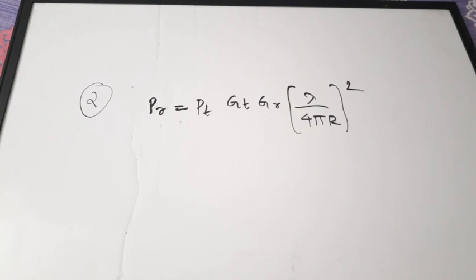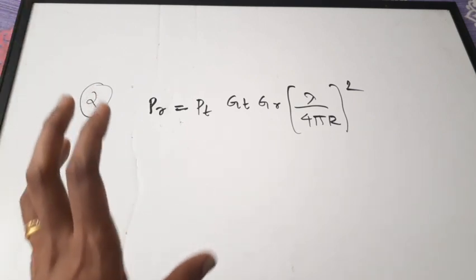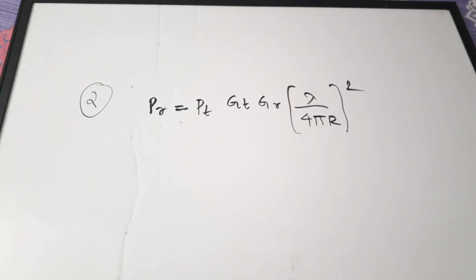Now, while substituting these variables, you should know that the values which are given in dB, you should convert it back to ratio. Okay. So the gains, if you see, are given in dB, 25 dB and 30 dB, but you cannot substitute 25 and 30 dB directly into this equation because the equations are derived by substituting the ratio gains. Okay. So this is one common mistake which students make while doing these type of questions.